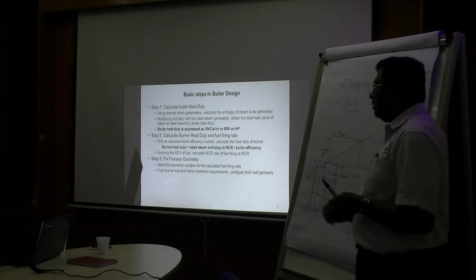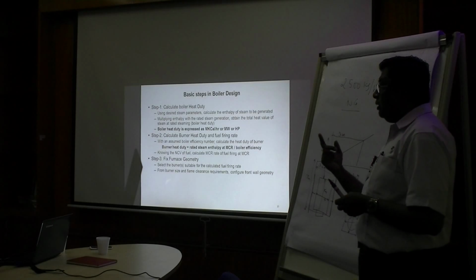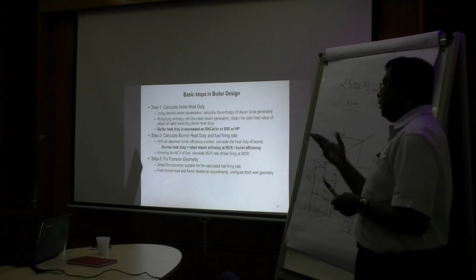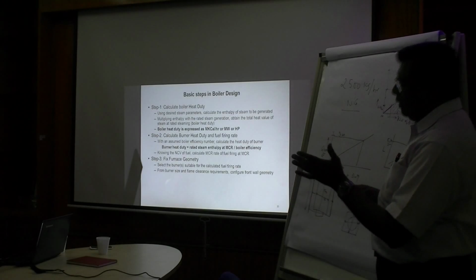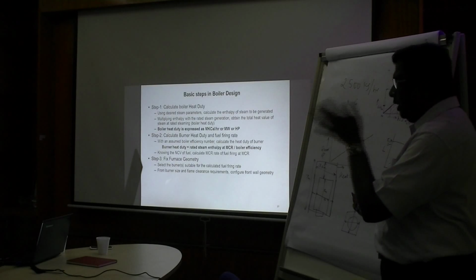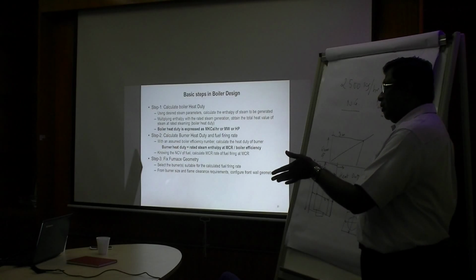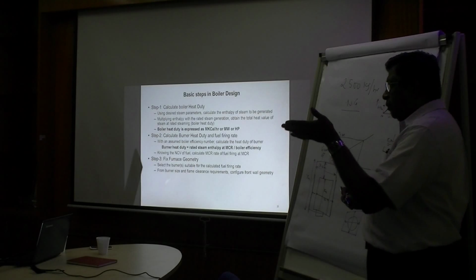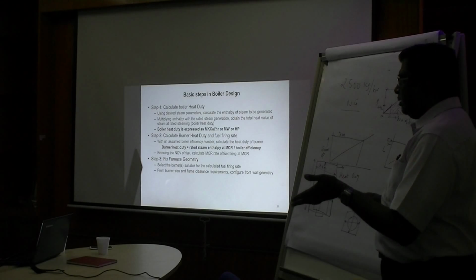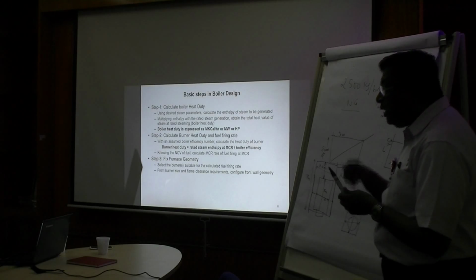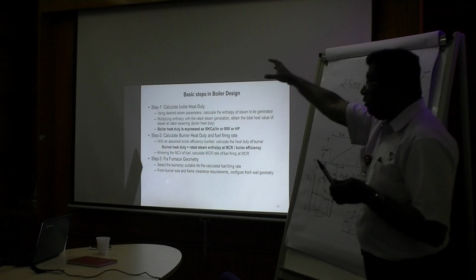It's bigger than our boiler, as a starting fire. It's one burner designed for 190 ton delivery, plus peak load of 10%. And you can imagine for lighting up that burner, you require, let's say, 20% of the minimum load. So 190 plus 10% is about 210. 20% of that is like 40 tons, 40 or 45 tons. So imagine it is bigger than the starting point from coal. The first fire in the burner is taking fuel more than our whole auxiliary boiler.